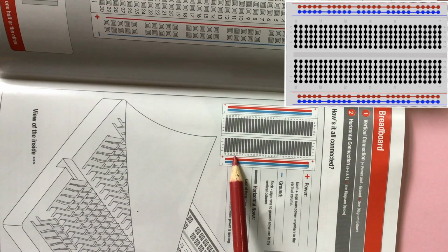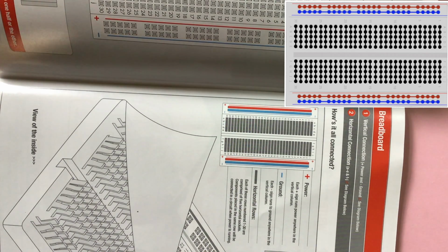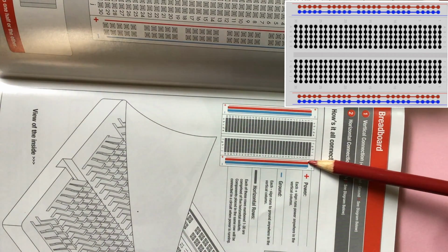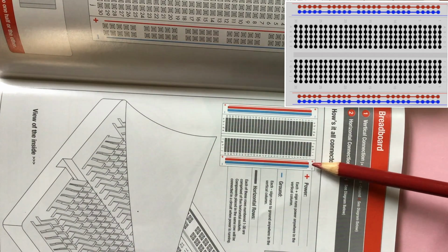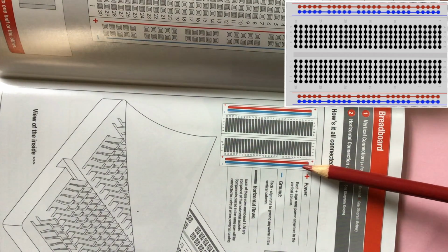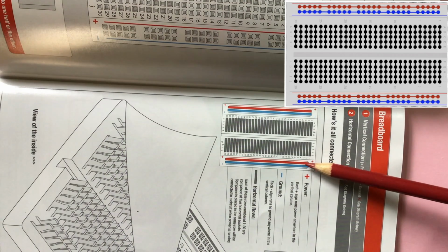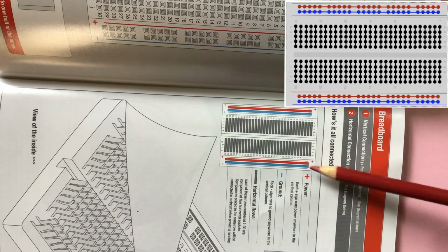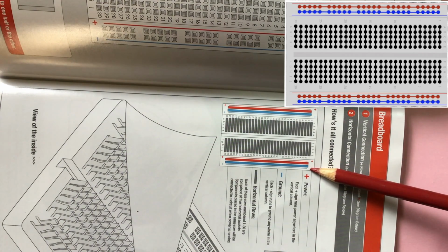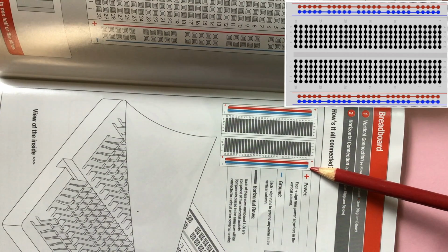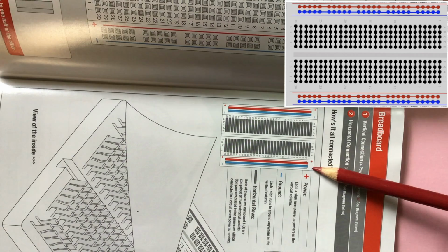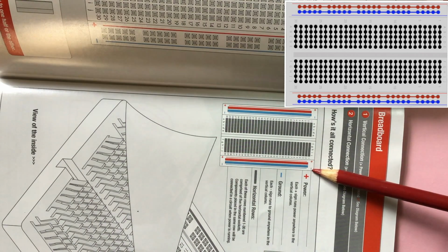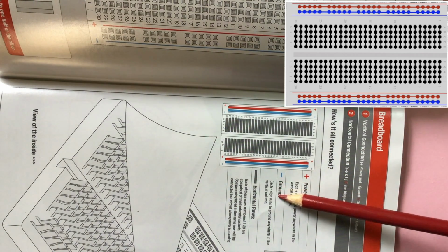So it's always good practice to connect the wire from the positive to this end, so that anything that needs power will be tapping it from the dots along this line. And at the far end, you will be connecting a black wire where there is minus. That black wire will be connected to the minus, to the negative. The negative in electronics, we also call it ground, as you can see there.